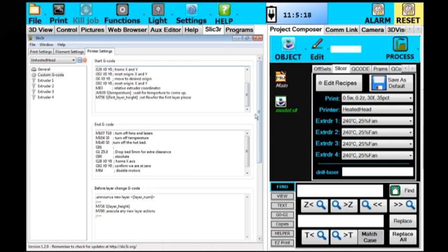You can specify a variable for just a tool change, and you can specify a variable for just between printing and non-printing moves, and more iterations of that same variable multiple times if you're doing tool changes, because your head may be sitting idle for several minutes.